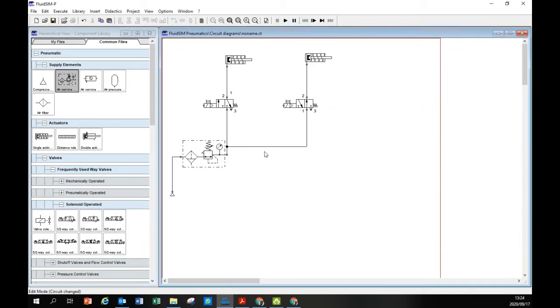These are pneumatics. That's why we say electro-pneumatics. They breathe. You send air into your devices and you are able to exhale that air so that your components don't remain with air inside them. So this system can breathe. You put air in and you need to take that air out into your atmosphere. With hydraulics, it's a closed system. You can't release that air.